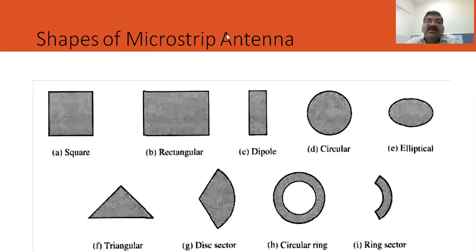The question, I think Akash has put, is that an antenna having gain of 6.7 dB and front to back ratio of 11.7 dB and resonating at 2.45 gigahertz is suitable for some specific application. So this is an antenna design problem.